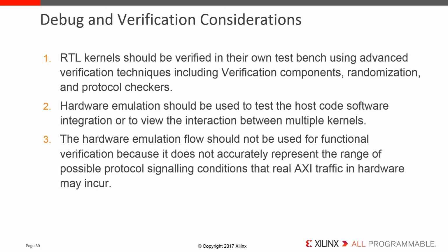Finally, let's look at some debug and verification considerations. You should do as much of your testing as possible at the RTL kernel module level by itself. Run exhaustive tests in a simulation environment as it gives greater visibility. Make sure the kernel is fully tested and verified and is AXI protocol compliant. Then make sure you can run hardware emulation on the design to test the integration and view the interaction between the kernels. Remember, don't rely on the hardware emulation for functional verification. It's mainly an integration test and not a functional test.